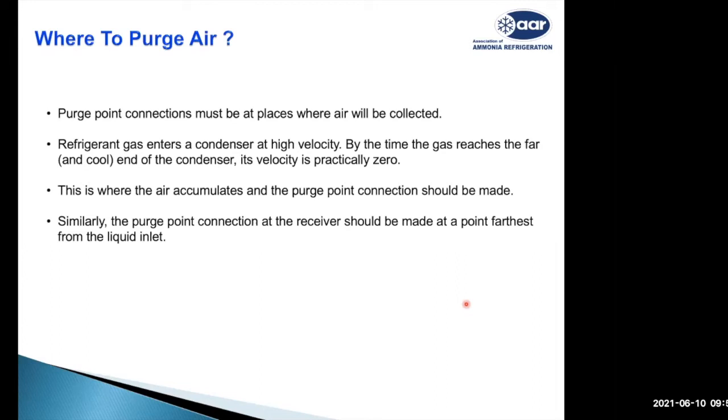So if I use this point to remove the air, then I will be able to purge more air than at the inlet. If I try to purge from the inlet, then the possibility of ammonia coming out is much more than the air.